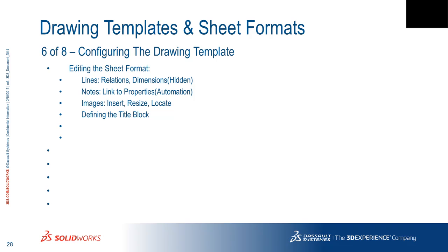The one you don't want to try to do is material. Because material is assigned to the part, and when you do that, you right-click on it, and you pick from your favorites, or you go into the material database and you pick from a longer list. Imagine trying to do that from a drawing in a field in a title block. I'd need to somehow dig back into the part, right-click on the material, pull up a database, show me the list, show me my favorites, all that kind of stuff. It's too much for SOLIDWORKS to handle right now.